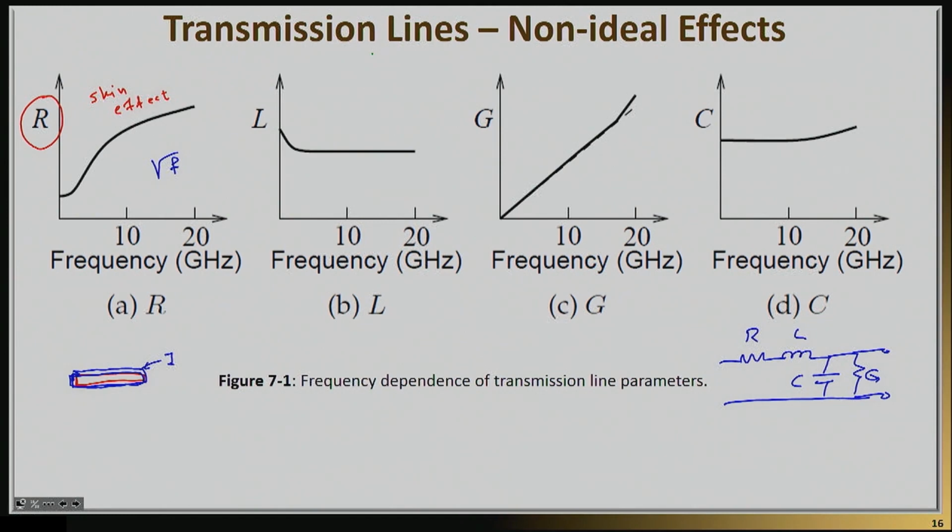Similarly, if I jump to G to talk about the other effect of loss, the dielectric loss also increases as a function of frequency. And that is true for any dielectric. That's related to the material issues. You can imagine, for example, that when you polarize a dielectric with an electric field, and you shift that electric field as a function of frequency, you make these dipoles actually reverse polarity. But when that happens, there is friction and there is loss. Hence, by the way, microwave cooking works.